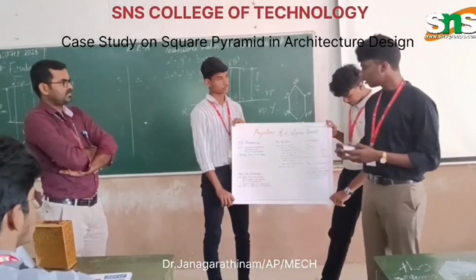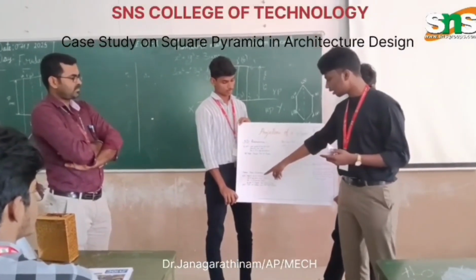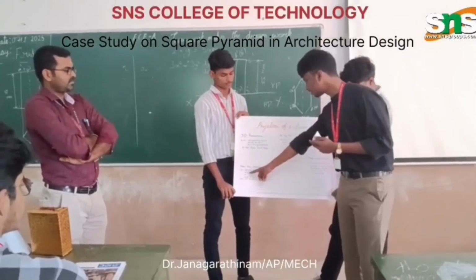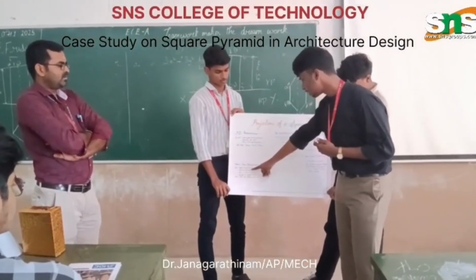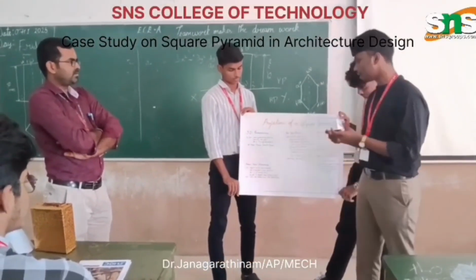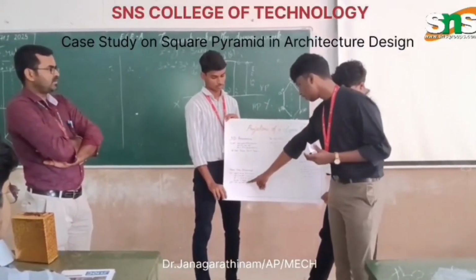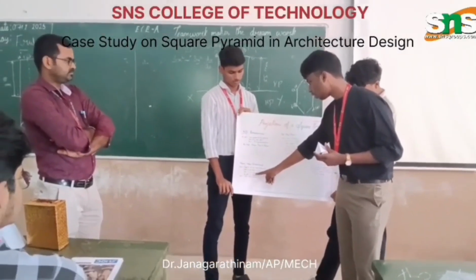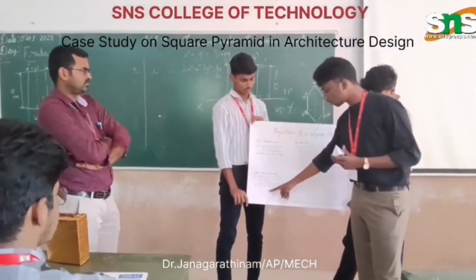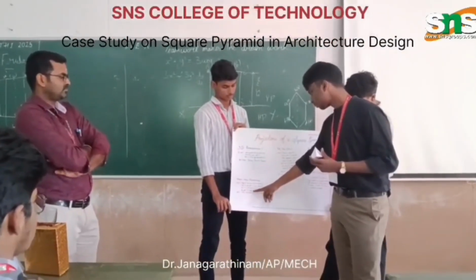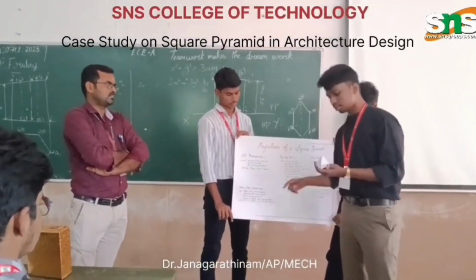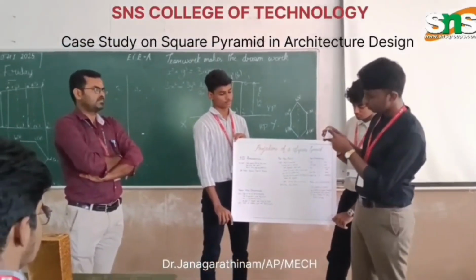Here is the front view, the elevation. Project the base line ABCD horizontally. Mark the apex point V 50 mm above the base. Join V to all the base corners. Here we connect all the corners to the apex. This gives the triangle shape, showing the true height, the true height of the triangular face.